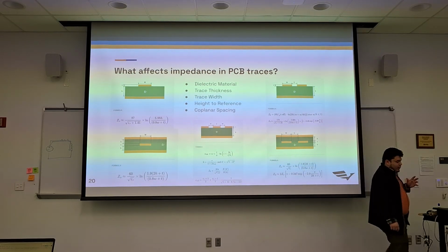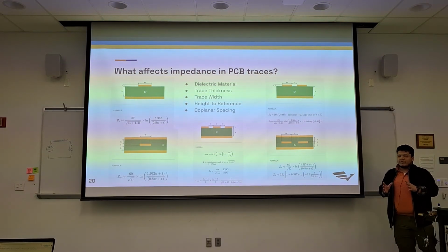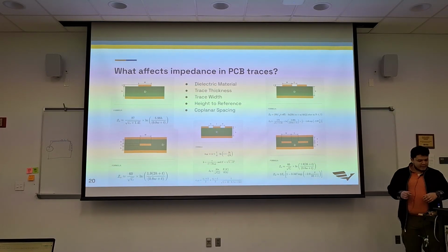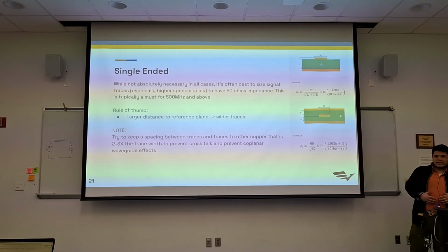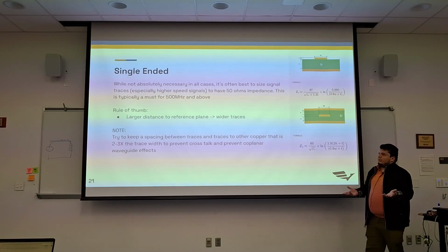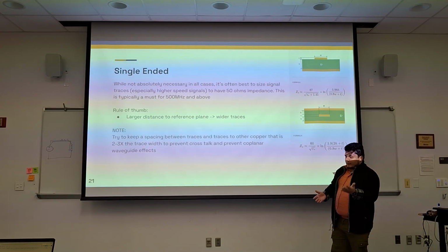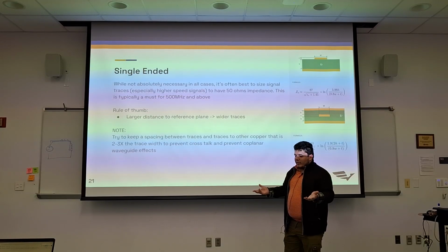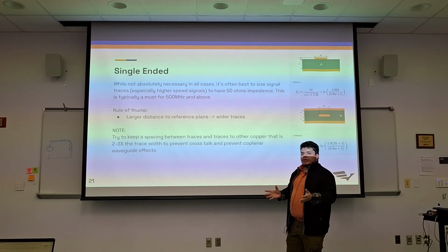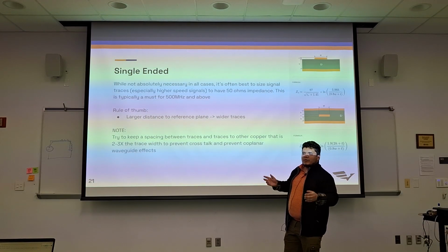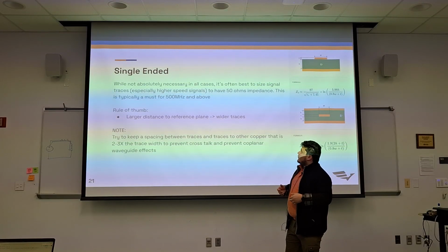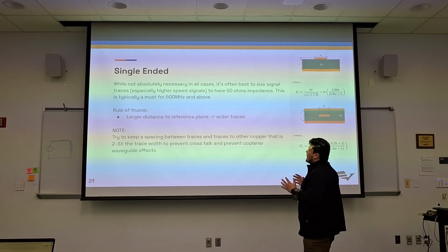And so this is why it's important that we are confident in our stack up from the very beginning, because now that we have all of the information from our stack up, we need to find how big to make our traces. Because when I'm making a connection from point A to point B, we want to make sure we've designed for the connection and not just an arbitrary, 10 mils looks good enough, right? Or maybe 8 mils is good enough, right? We want to make sure that we can back up what we're designing.